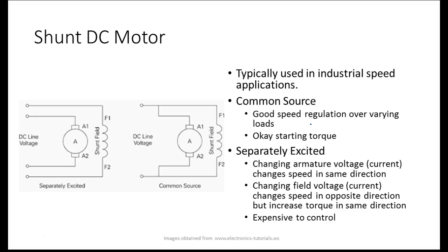They won't start, but they could run away, right? Understand? Because as the field goes down, as the torque goes down, speed does what? Goes up. So between the two, we can have a really, really good controllable motor.